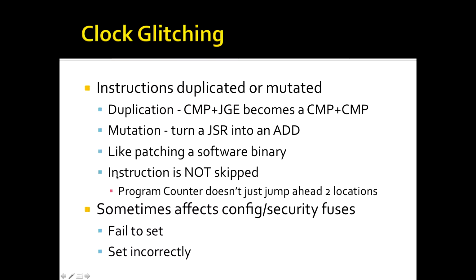So sometimes this quick burst of clock frequency can affect your config or security fuses. So they'll either fail to set in some cases, or they're set incorrectly. So this could actually be kind of helpful to wipe out some certain code protect fuses or things like that. But it's a lot more particular in how it works, depending on the device.